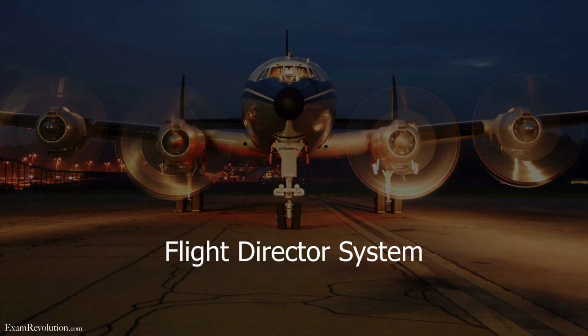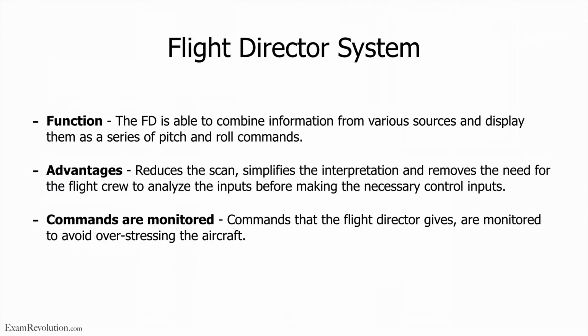So let's talk about the flight director system. Now, I've already actually spoken quite a lot about it, and I've shown you the different things, and how it works. But the function of the flight director is it's able to combine information from various sources and display them as a series of pitch and roll commands, like you've seen, right? The cross or the bat wings.